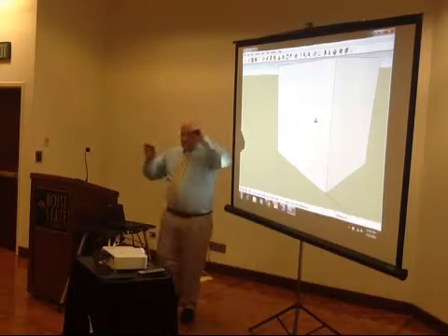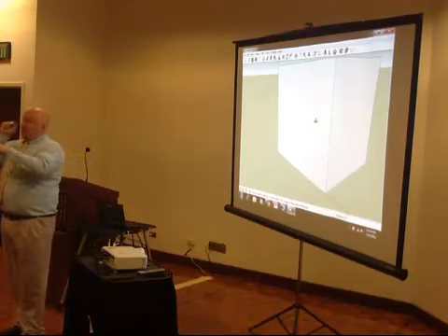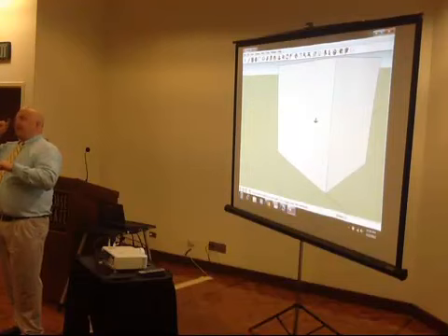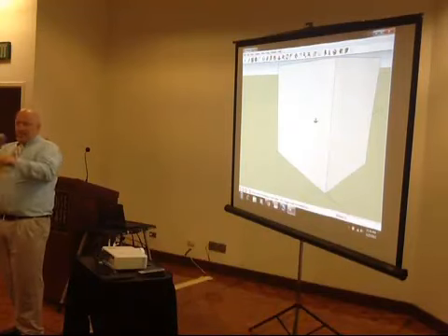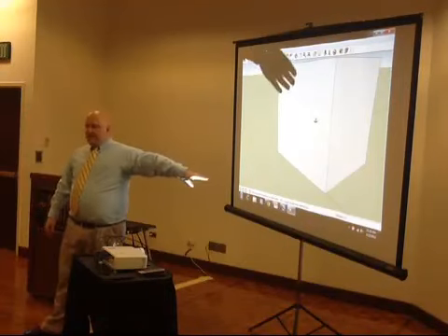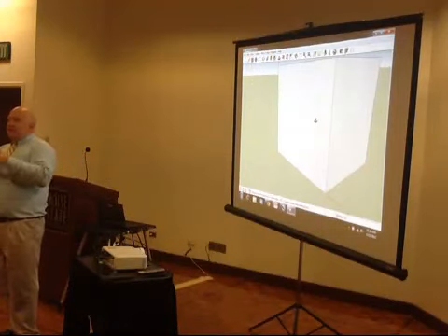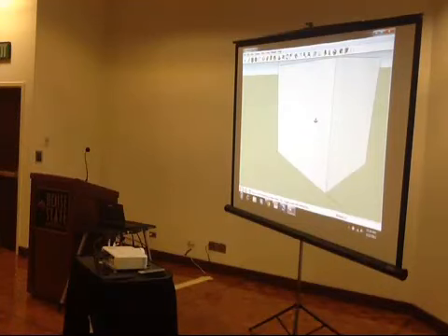So review that again. I take the push-pull tool, I click on my shape and start to extrude it. But I haven't clicked again yet to say I'm finished extruding. I just let go of my mouse, and then I type the measurement that I want. SketchUp will pay attention, and then you say whether it's feet or inches, hit enter, and it will complete the extrusion at that height.